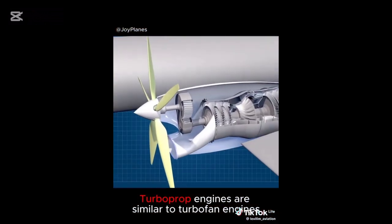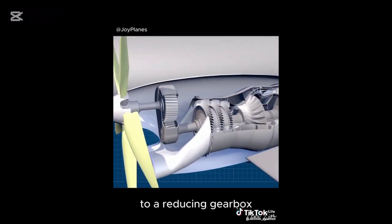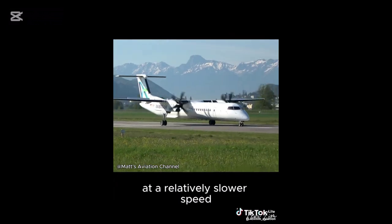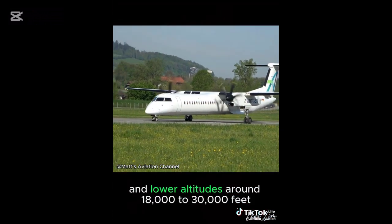Turboprop engines are similar to turbofan engines, but instead of producing thrust from exhaust gases and the fan, the energy is sent via a shaft to a reducing gearbox which connects to a propeller. Since turboprop propellers rotate at a relatively slower speed, turboprop aircraft are more efficient at lower speeds, around 250 to 350 knots, and lower altitudes, around 18 to 30,000 feet.